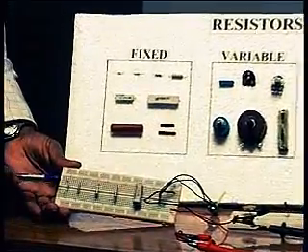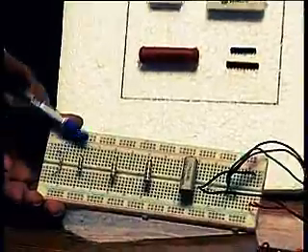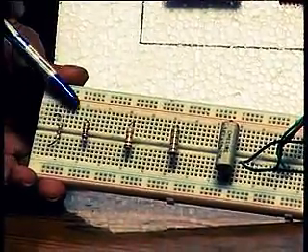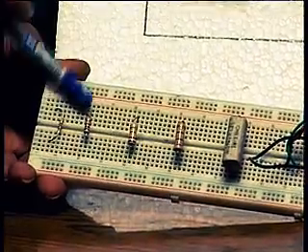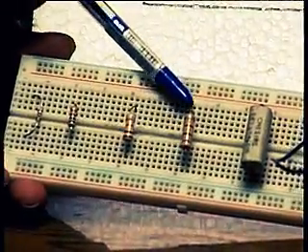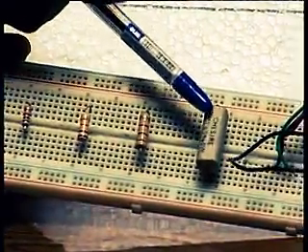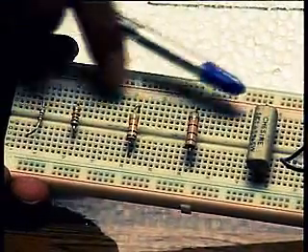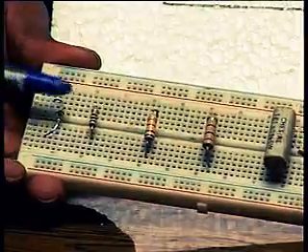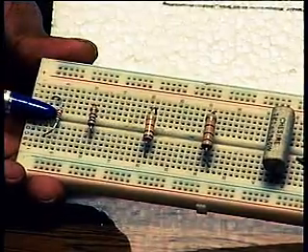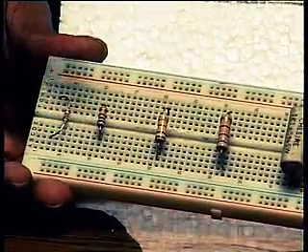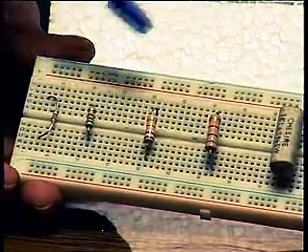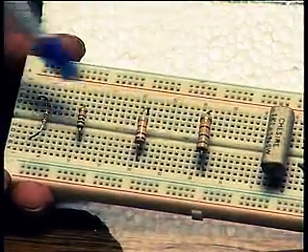For example, here you can see resistors with different wattages. This is about 1/8 watt, this is quarter watt, this is half a watt, this is 1 watt, this is about 10 watt. This is a ceramic resistor that I mentioned to you. You can see the sizes are also increasing corresponding to the value. Some of the values are almost same. For example, this is 1000 by the color code, this is also 1000, I think this is also 1000. So many of the resistors are all of the same value, but the size is different